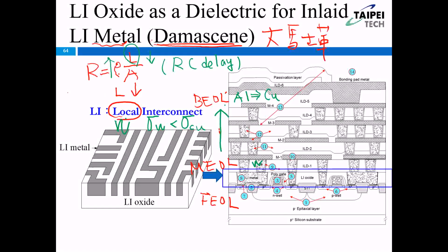So right now, after we etch the silicon dioxide, we generate the space for the copper to fill in. We fabricate the space here and here, so later the copper can fill in this space. Okay? The next step, we electroplate copper, 电镀, into this space.